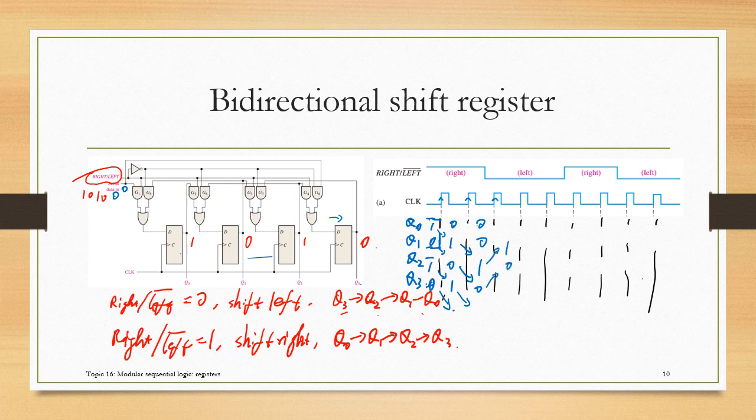This won't be here. This 0 will be here. So this 0 will be out. This is stored in Q0, but it shifts out. And the data in now is loaded to Q3. So we got 0 here. All right. Then shift left again. So we have 0, 0, 1. We have 0 here. Then shift left again. We will have 0, 0, 0, 0. Actually, we don't have to do the rest because it's all 0.